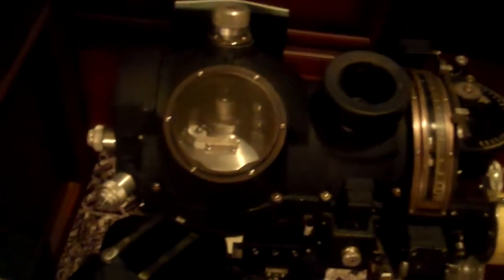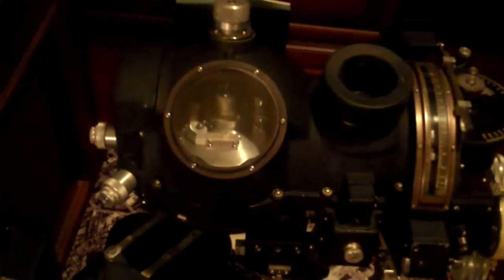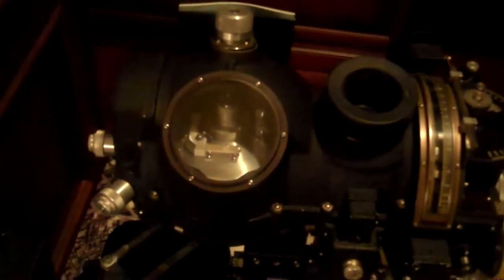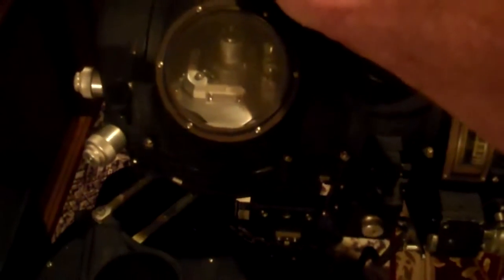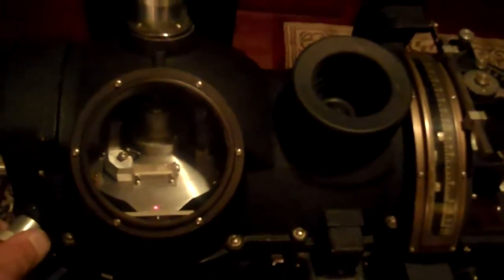The bomb sight is now faced straight on to the target, and the aircraft is flying the correct course straight to the target, but the aircraft is angled into the wind. The bomb sight gyro is now uncaged, and this allows the leveling bubbles to level the gyroscope. This also moves the telescope so that it is now vertical to the ground.